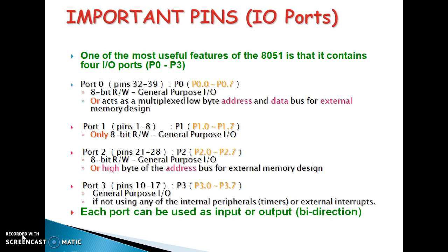These are some important pins used for the input-output ports: port 0, port 1, port 2 and port 3. Port 0 is 8-bit read-write, port 1 is only 8-bit read-write, and port 2 is 8-bit read-write general purpose as well as the high byte of the address bus for external memory design. Port 3 is general purpose input-output.